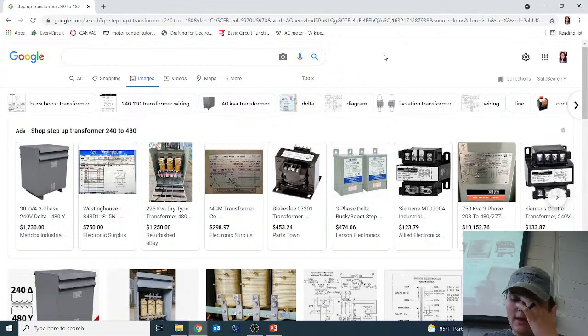Alright, and checking transformer resistance. A DMM set to measure resistance can be used to check for open circuits in the coil, short circuits between the primary and secondary coils, or coils shorted to the core, without power applied to the transformer. So, open circuits in the coils. The resistance of each coil is checked with a DMM.